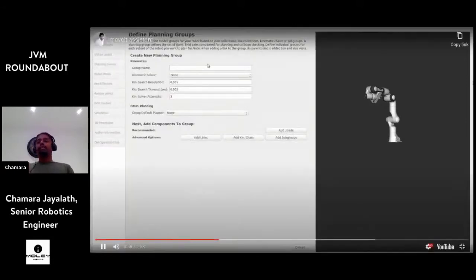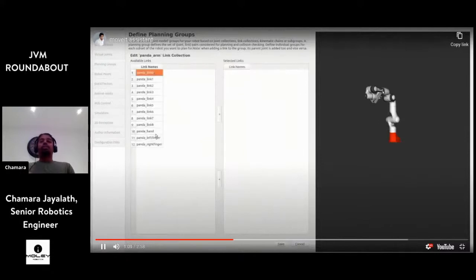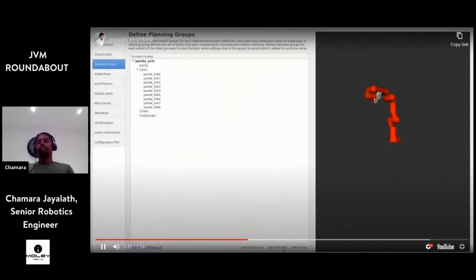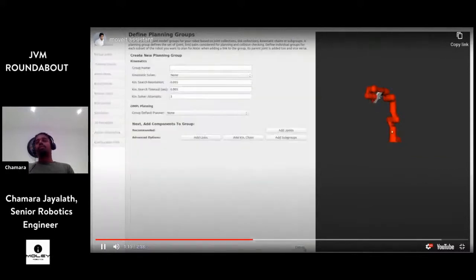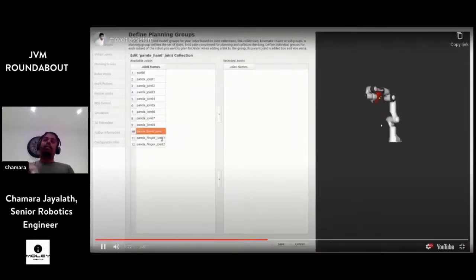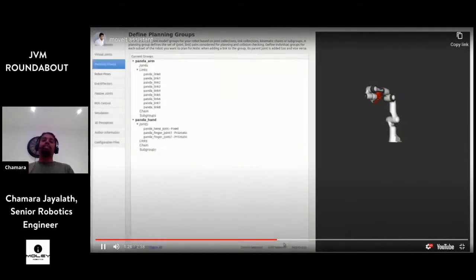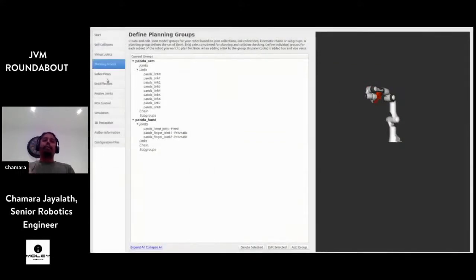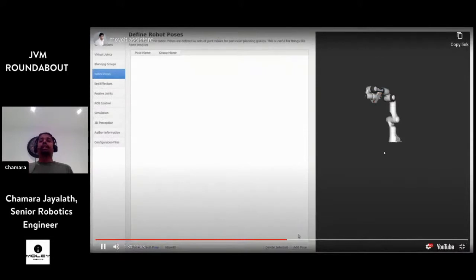And then as you can see here, our robot has a gripper and also this actual robot arm here. So I can define different groups here. I define here from the base to the last joint. So this is one move group that we use for all our planning and so on. And then I can also use my gripper separately and configure it in MoveIt, and it will be used as a separate group. Yeah. And so this is done now.